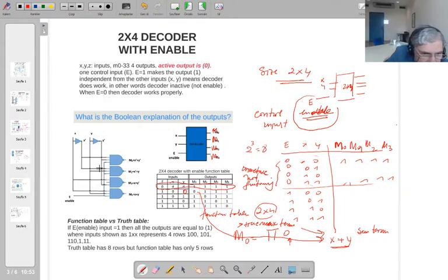So it goes like that. Look at here. When you apply x and y here, this is a NAND gate. So you're applying here, the order should have been different, isn't it? So x prime and y prime is here when the enable is 1. So first, let's see, when enable is 0, all these NAND gates have one of the inputs 0. 0 multiplied by anything gives you 0. The complement of that 0 gives you 1. So that means when enable is 0, your outputs are going to be 1.